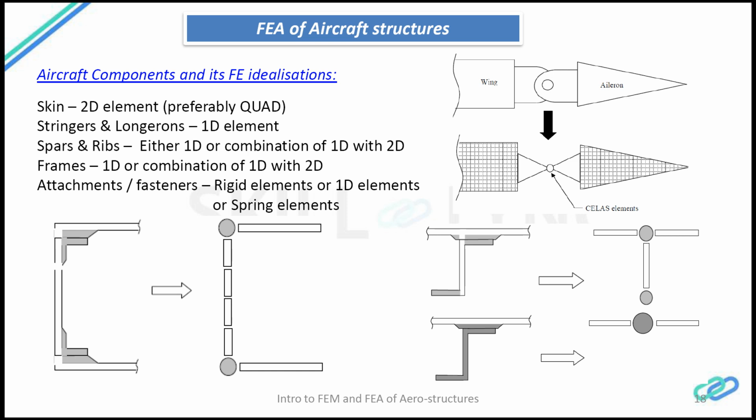One has to be aware of the critical load paths. What are all the members of the structure that take most of the load, and what doesn't take load, or which is a non-structural panel. Suppose on the fuselage you can see small access holes or access panels. Access panels are non-structural panels, so it depends on what you should model within the tool and what you shouldn't. You should have a very clear understanding.